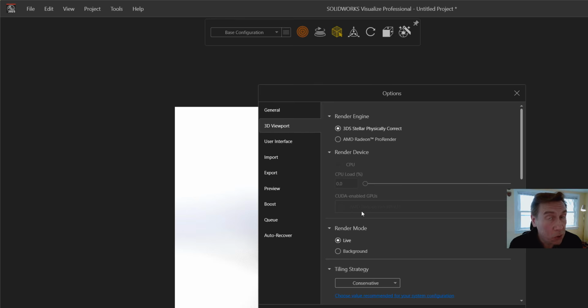And those of you who know about CUDA cores from graphics cards, the thing is that the CUDA cores might only work from up to the 10 series or newer, might even be newer than that. Maybe the 2000 series might be CUDA cores, and those might be still usable, because I've had older graphics cards from 2016, 2015, and the CUDA cores were too old and the renderer didn't want to utilize it. So just be aware.